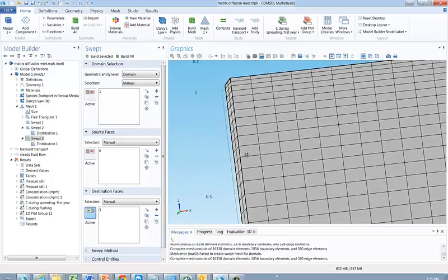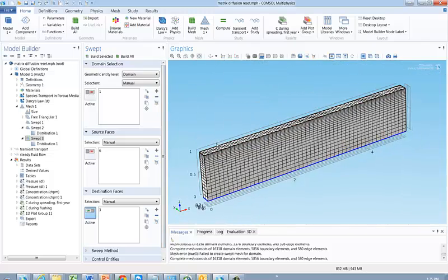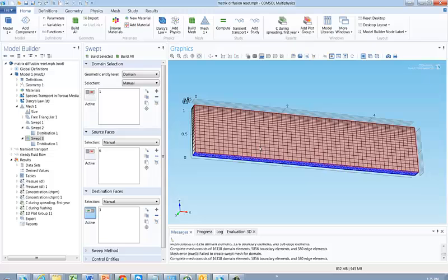One of the things that you'll find is that you need to be able to go from this surface to the surface down here without there being any interruptions along the path. It doesn't have to be straight. It can certainly be curved, and that's one nice application for this kind of mesh, on curved geometry like a pipe or a tube, but it does have to be continuous. If I were to put a point here or put a little subdomain region in here, then I couldn't use a swept mesh. So it's not for all cases, but it's quite useful when you can implement it.